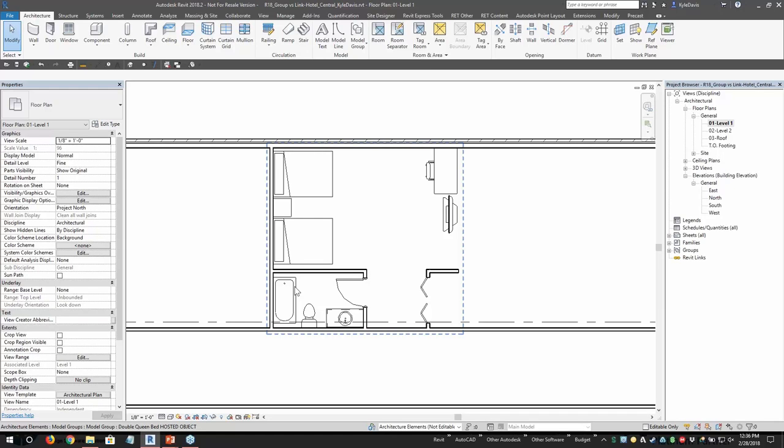So if you were to do hosted, face would be the best one because again, if the element's not there, face-based objects sometimes just become orphaned objects. Whereas wall hosted, ceiling hosted, floor hosted, those objects are required to be there in order for it to work. So if possible, face hosted would be the second best, non-hosted would be the best.